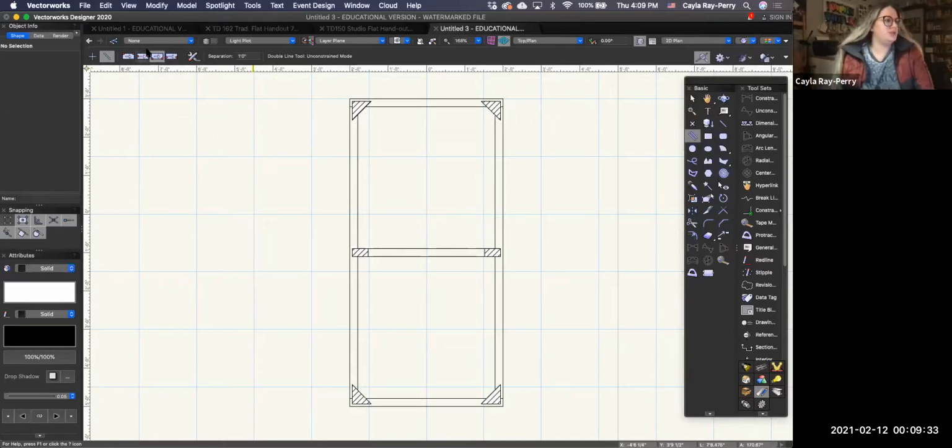These red dots indicate your click points. Right now I'm on this setting, meaning that if I click the line, the second line is going to pull out on top of my click point. I can also have it draw from the center. So I click on the center and then it comes out, or below or at a fixed point.